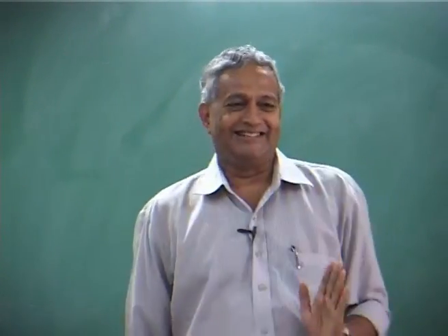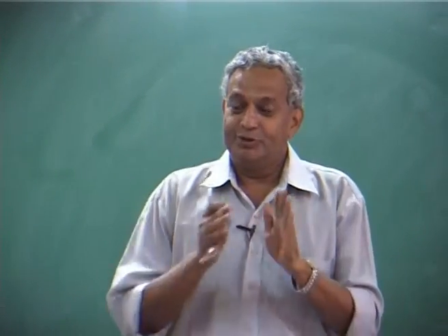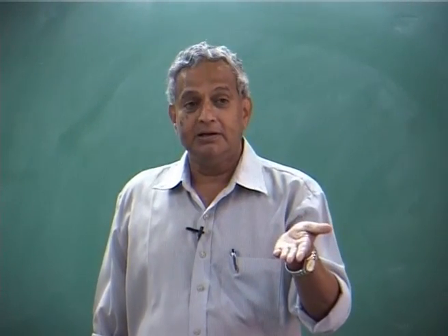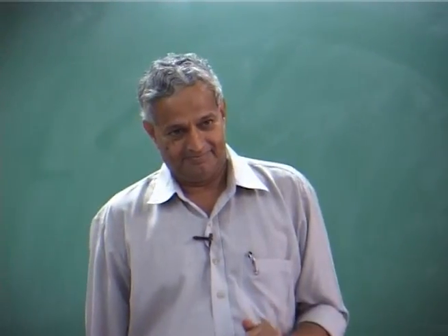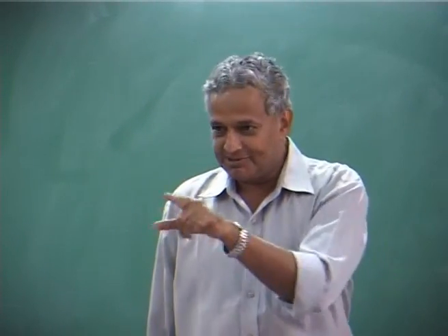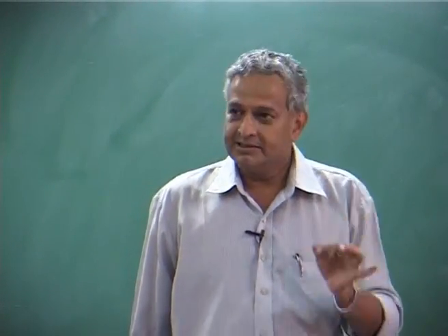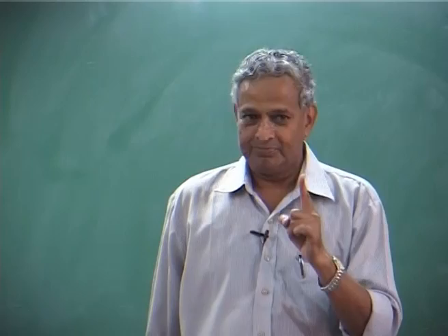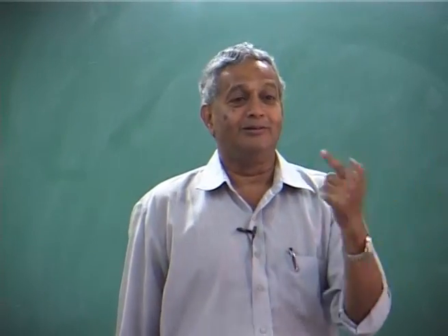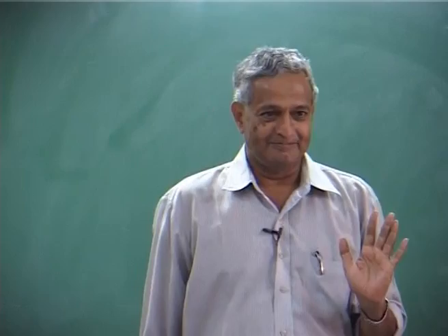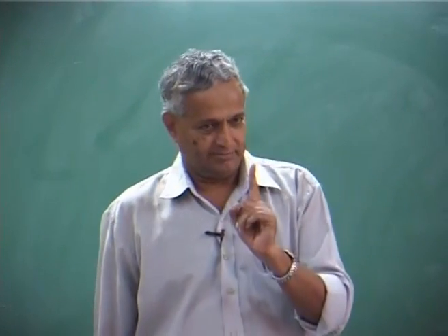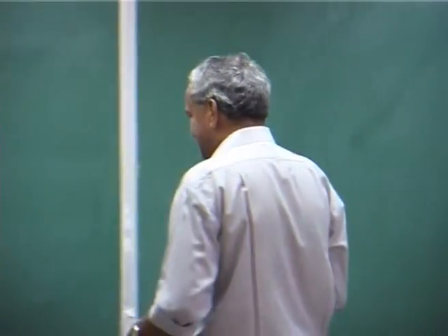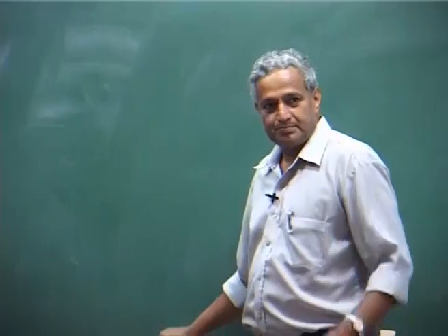We will come to that later, because you are observing the flap motion from a non-rotating frame. You understand? But right now the equation which we have written is observing the motion of one blade as it goes round and round. Okay, is it clear? And it does the same motion, please understand. That is why we wrote beta equals beta naught plus beta 1c cos psi plus beta 1s sin psi.